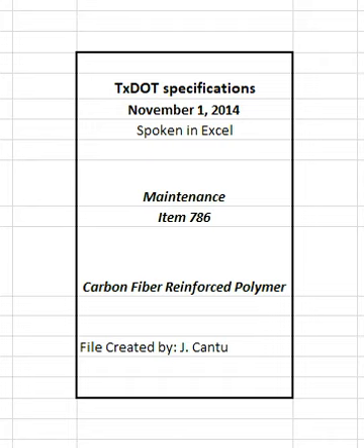3.3 Concrete structure repair. Perform concrete structure repair in accordance with Item 429, Concrete Structure Repair, as shown on the plans. Allow enough time for concrete repair material to cure in accordance with the CFRP manufacturer's specifications before placing CFRP. Repairing surface defects to ensure required contact surface condition is not considered concrete structure repair and is required work for this item. 3.4 Surface preparation.